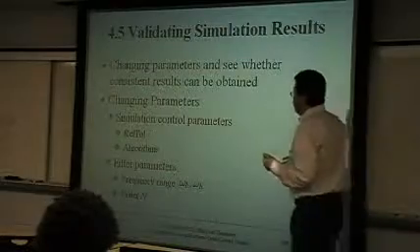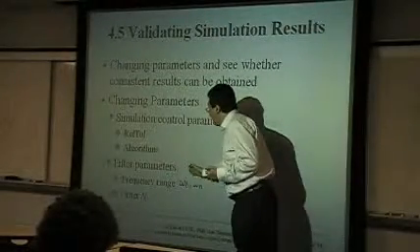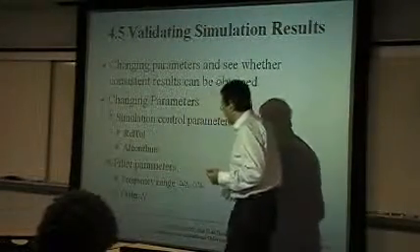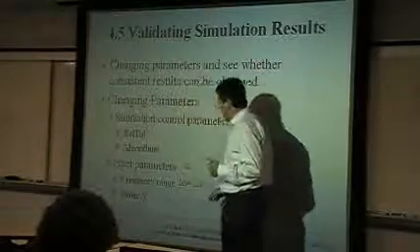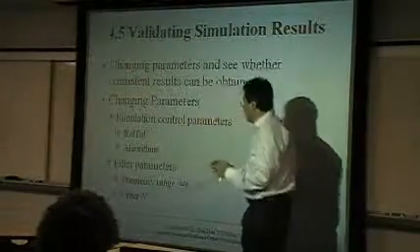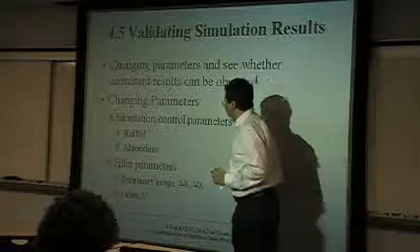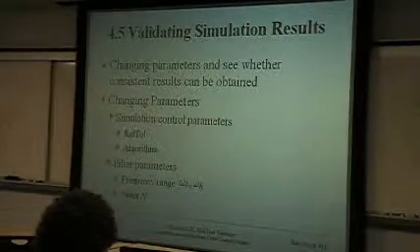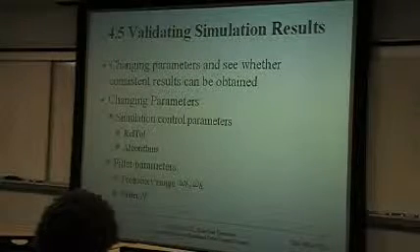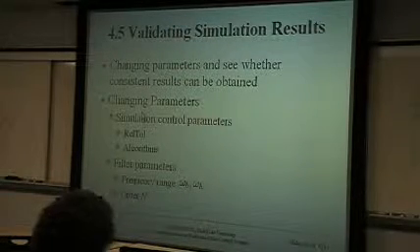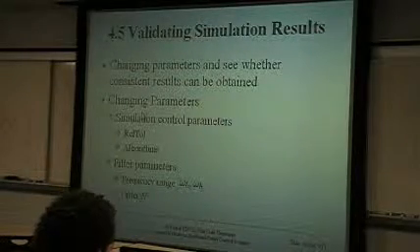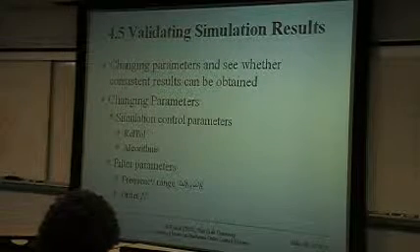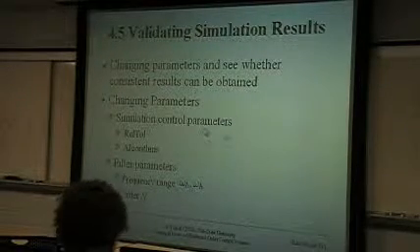And the other method is to change the parameters in the filter. For instance, we can change the orders of the filter, or change the frequency filter range, and see whether we can get the same results. If we can, we say that we get the correct result. If we cannot, we have to perform simulation and change these properties or parameters again.